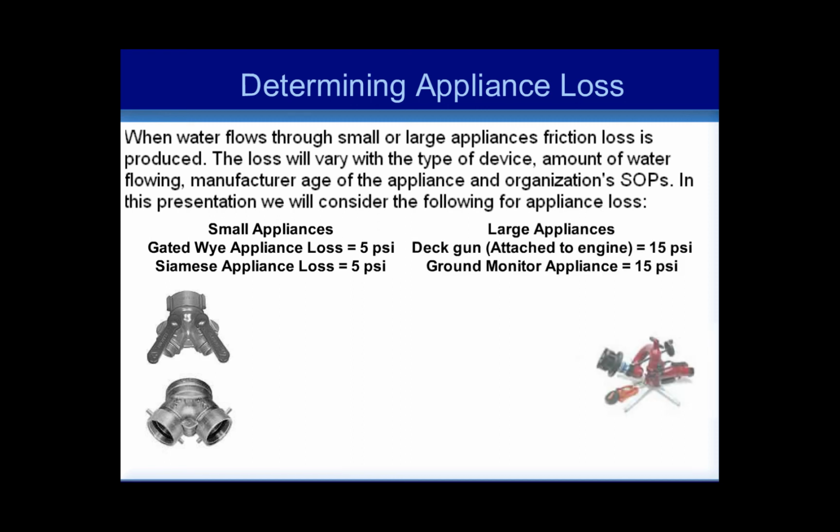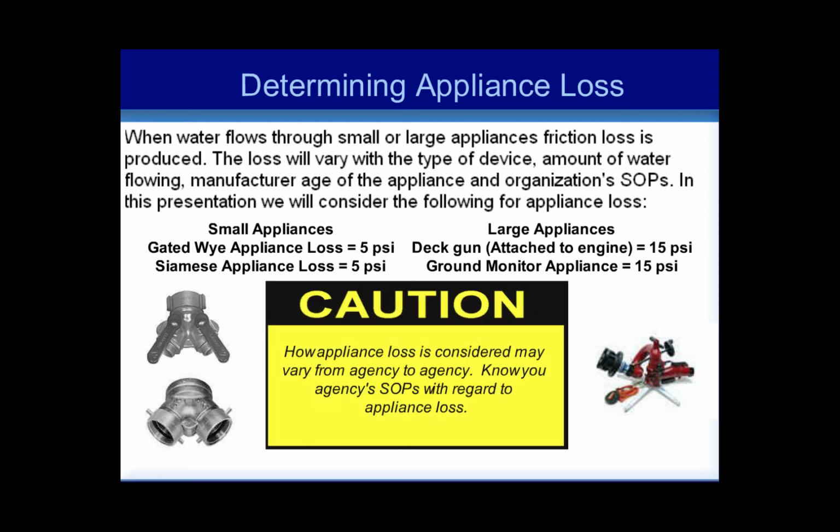Large appliances allow 15 psi for a deck gun attached to the engine, and also 15 psi for a ground monitor appliance. Use caution. How appliance loss is considered may vary from agency to agency. Know your agency's SOPs with regard to appliance loss.